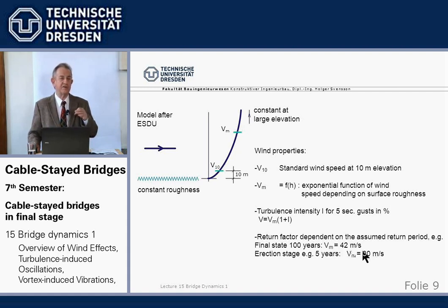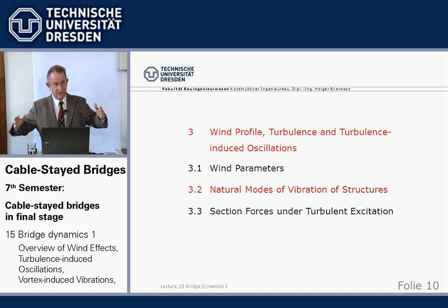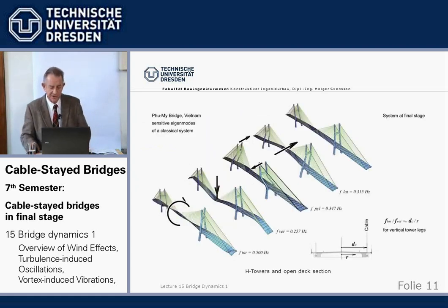Of course, there is no guarantee that the 100-year probability will not occur during construction, but then the factor of safety must come in. So we have on one hand the wind blowing onto the structure, on the other hand we have the structure itself reacting to the wind. And the most important reactions are the natural frequencies or eigenfrequencies. The most important is the vertical bending, which typically is here 0.25 Hertz,